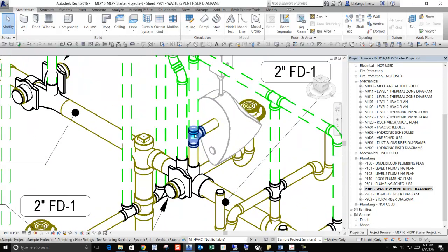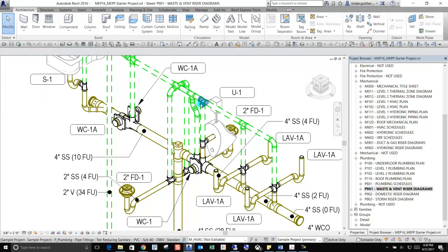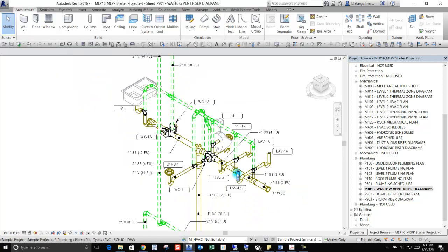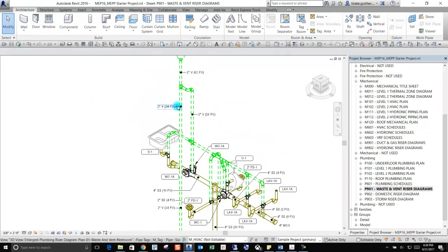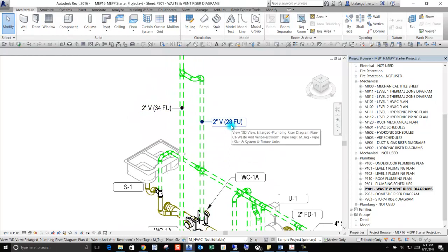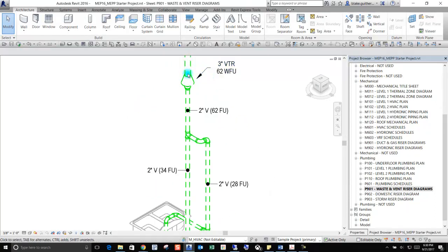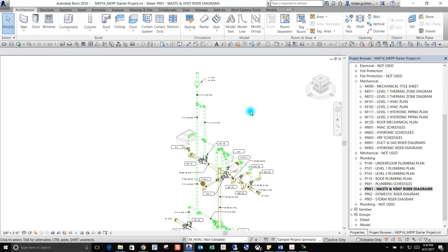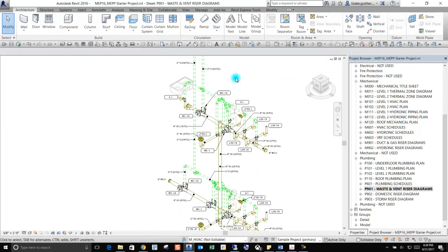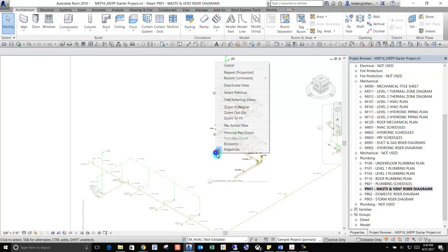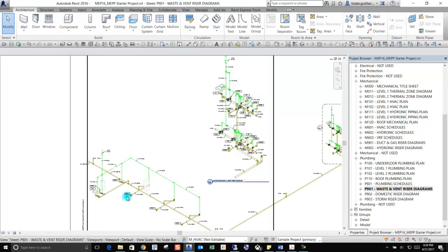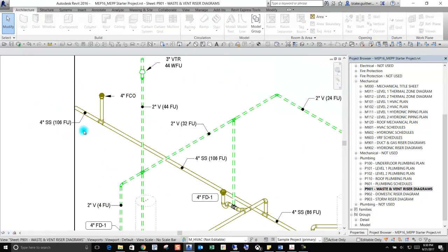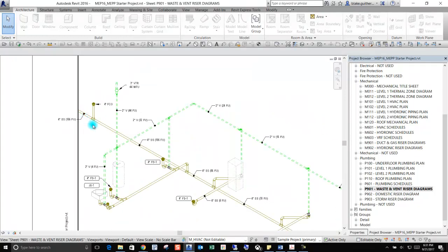These special split system connectors separate sanitary from vent, and then a vent sanitary system classification will actually calculate the flow. And we're able to get our total fixture units from the lower level and the upper level and going through the vent through roof. All dynamic, all easily set up for code and permitting requirements and things like that. So this entire waste system now flows all the way out to the service.